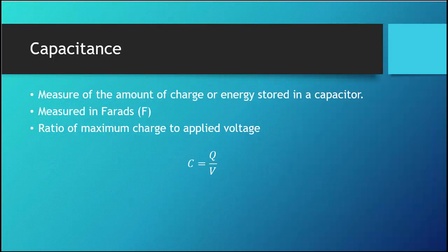And so, like we said before, they store energy. So the quantity of capacitance, which has a symbol of capital C, is a measure of how much energy or charge is stored in a capacitor. You measure it in farads. Farads are huge, and you're most likely to see microfarads, nanofarads, and picofarads. And pico is 10 to the minus 12. Just heads up on that.